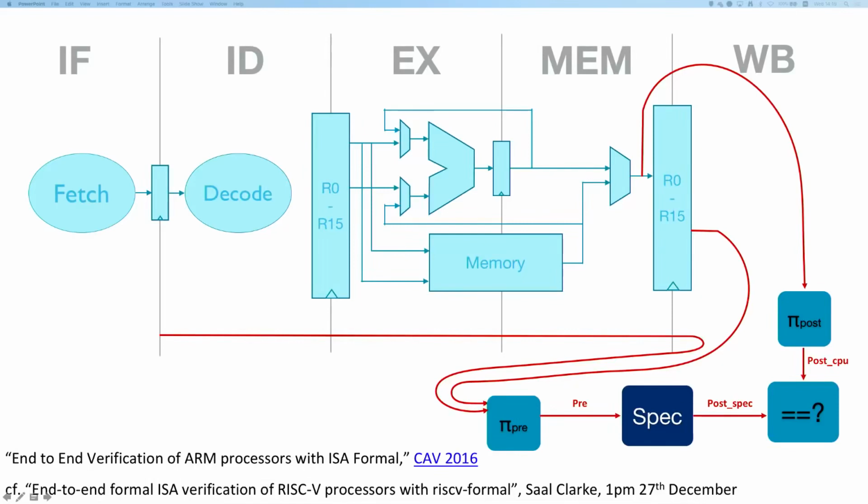And a bounded model checker is like one of those constraint solvers that I mentioned earlier on crack cocaine. So what it will do is it won't just try one step for what can happen, but will actually try multiple steps, all possible combinations of inputs for one instruction, two instructions, three instructions, longer and longer sequences of instructions, looking for ways that can fail the property.